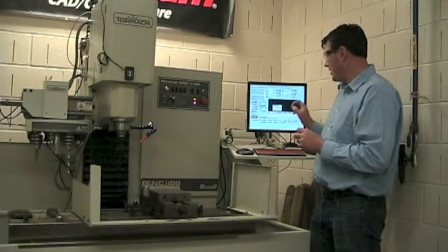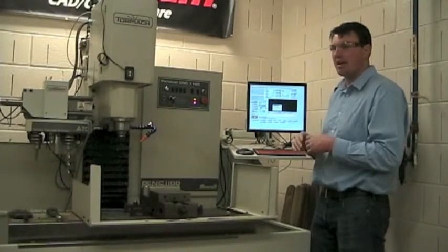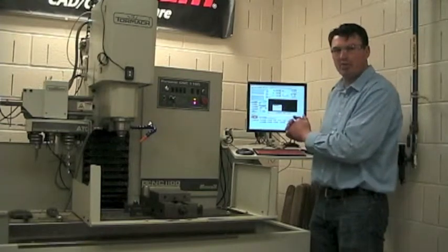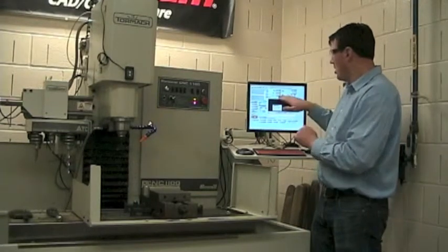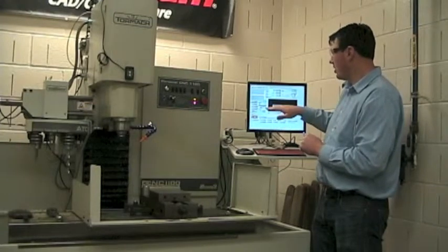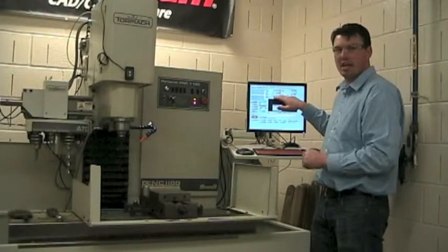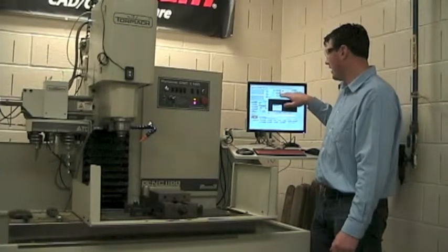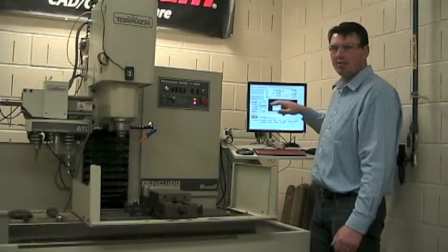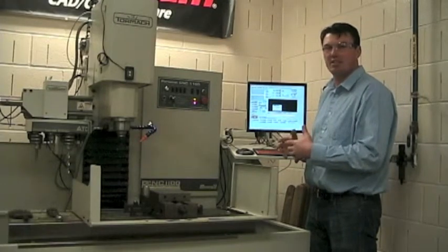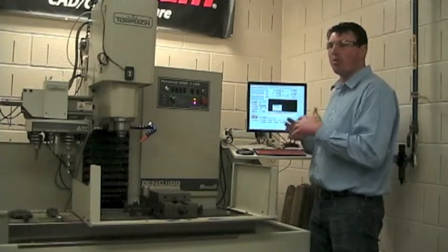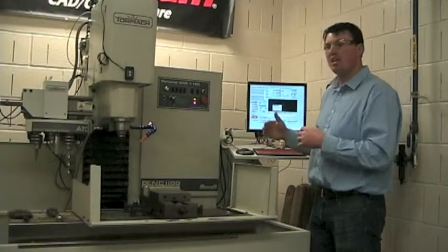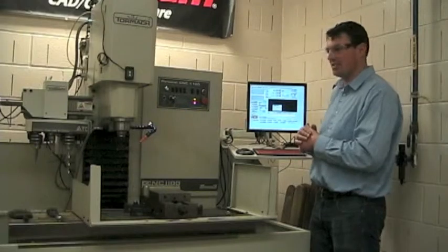It's then going to ask me if it's okay to reference the Z. Now referencing the machine, you'll see when we get into a close-up of this controller screen later in the video, but in my simple run screen I have my X, Y, and Z axis DROs, or digital readouts, and next to them I currently have red lights. Red lights mean that those axes are not referenced. Before we run any program or perform any operations with the tool changer, we need to reference those axes.